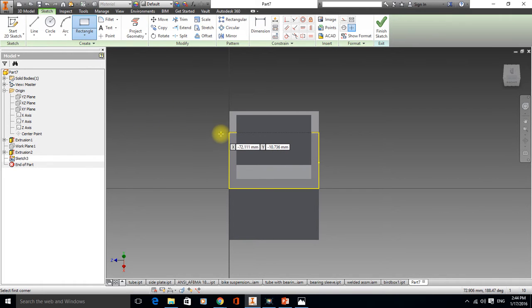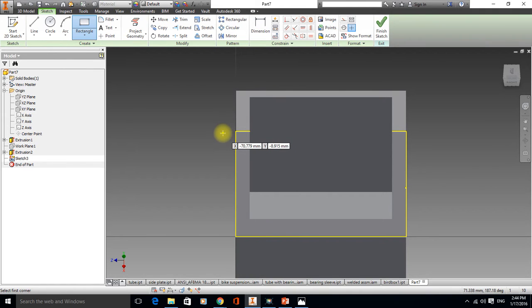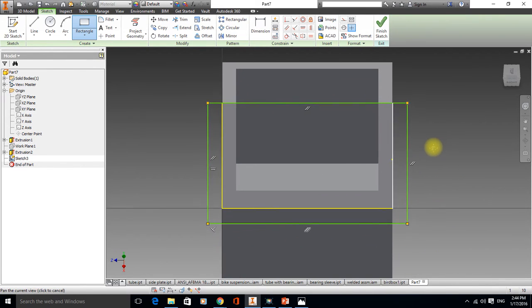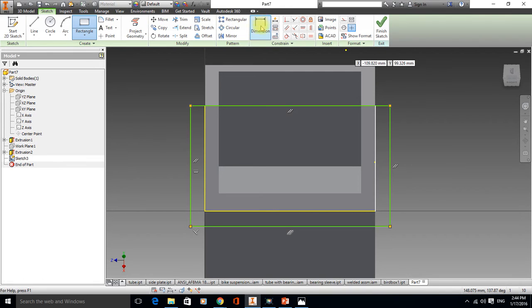Now I'm going to hover somewhere near the middle, and you can see there's a black dotted line going to appear, and that's snapping to that, and it's automatically snapping the top left hand corner of our rectangle to the centre line of our ridge. So let's click that and drag him across just beyond the bottom right hand corner. And now again, let's add some dimensions.